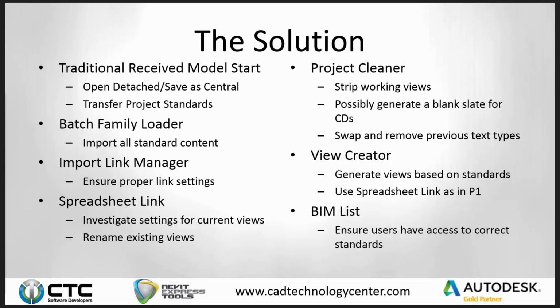which is to open the model or models detached and save as new central files. We're going to use transfer project standards. Those are out-of-the-box tools. We don't have any custom tools ourselves for this. We're going to leverage those tools, and I'll show you a couple of things you might want to take some notes on for interesting components that you need to make sure you bring across. And then depending on your discipline, there might be a few others as well.